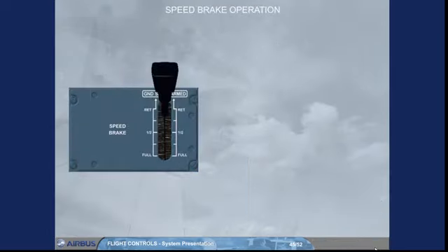To set the speed brake surfaces, spoilers 2, 3 and 4, to a required deflection, the speed brake lever must be pushed and moved rearwards to a position which depends on the required amount of drag. Note, at the half position, there is a hard point.